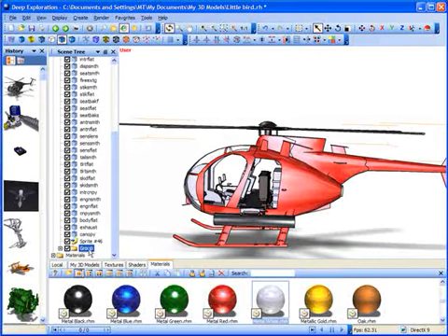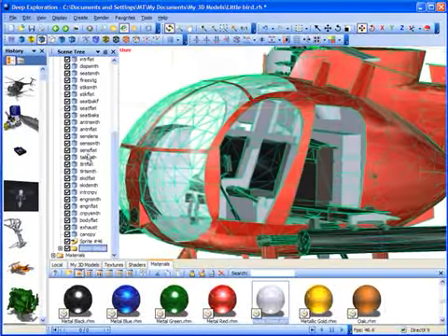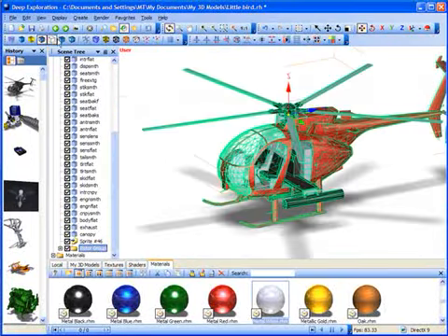So we can choose our top view for this helicopter. We'll now zoom in, and we're going to move this pivot position. This is the pivot point upon which the rotor will turn during our animations. So we're going to move this up using the handles on our gizmo. We can also go into wireframe mode, and that will help us locate the center. And we can see the center of the rotor here. So this should have created a center for the rotation of that group.